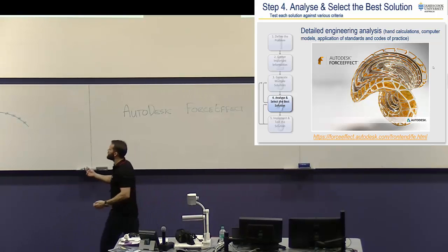The other thing, if you want to do something like a suspension bridge, I don't suggest that anyone does a suspension bridge because it's a bit dependent on fixing down here, but just as an example, you can do a horizontal member, have a weldment there and a weldment there to your verticals, so that's all solid, and then you can have pins to your sections like this, so that behaves like a cable, or like a chain, because it's got pins, it can do whatever, and with more pins, you can hang the cables down like this.